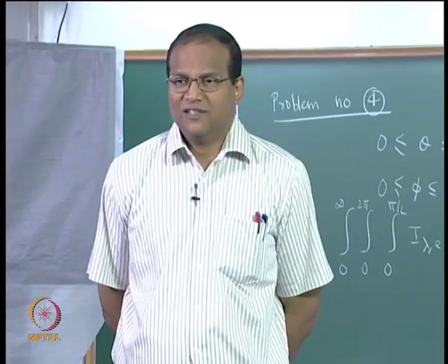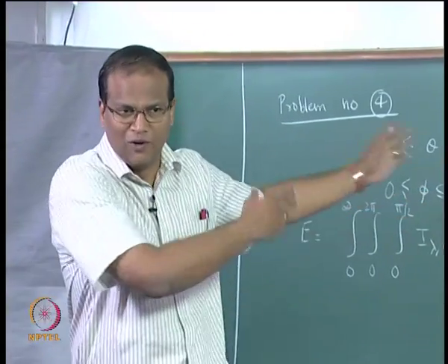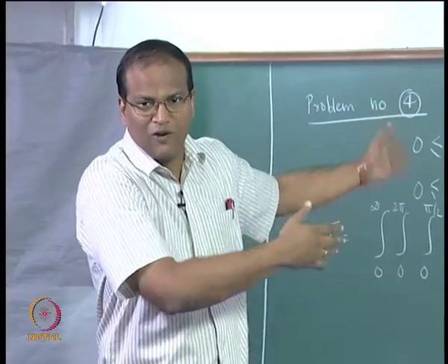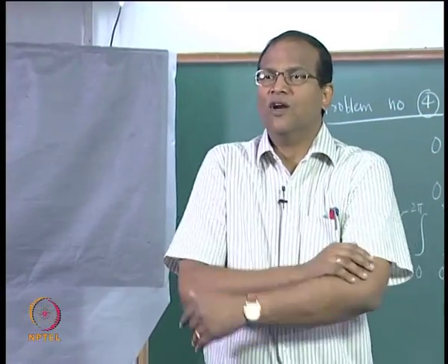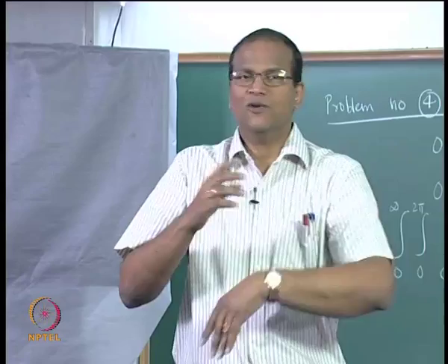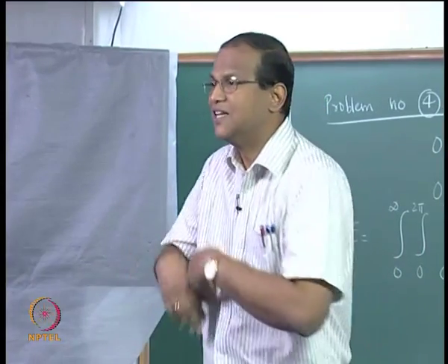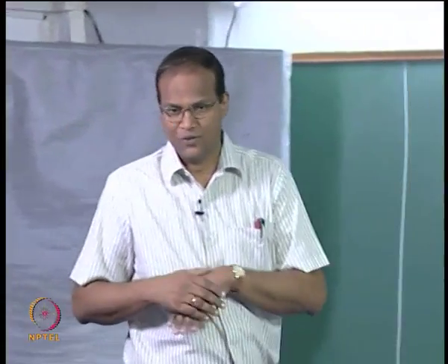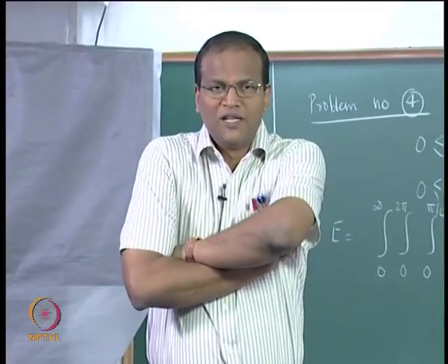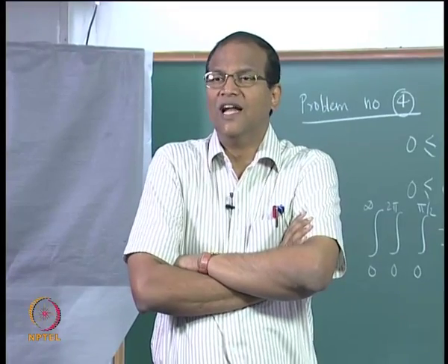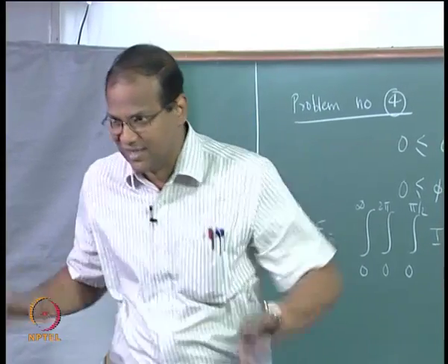If I is given, if it is diffuse we can find out what is a fraction, or between two bodies if E is given and if it is diffuse I can put E equal to pi IB, and find out what is the heat flux which is coming on the second surface, if you know what is the emission from the first surface and so on. But suppose I know only the temperature of the first surface, from the temperature how do I get E or I is something which I do not know as yet.